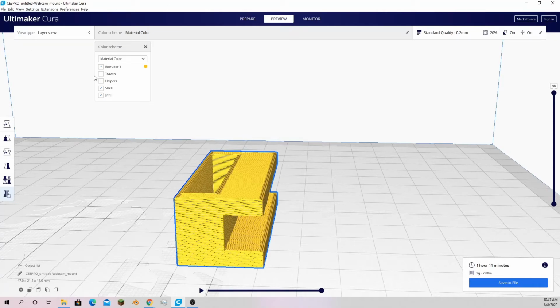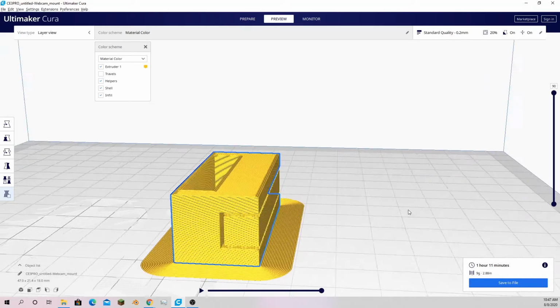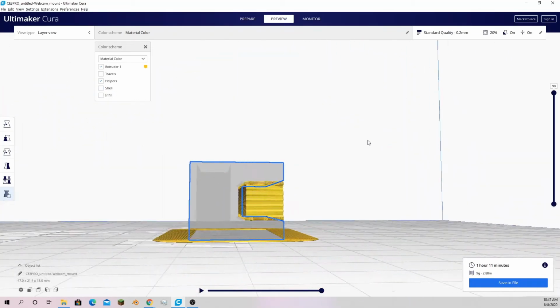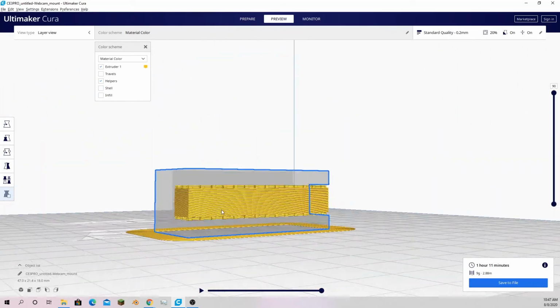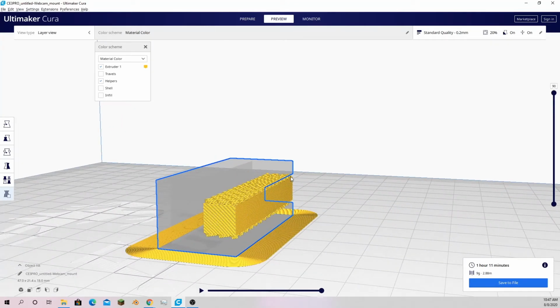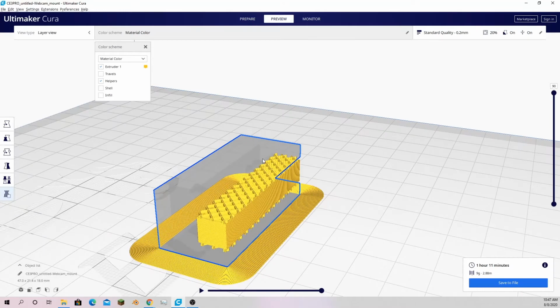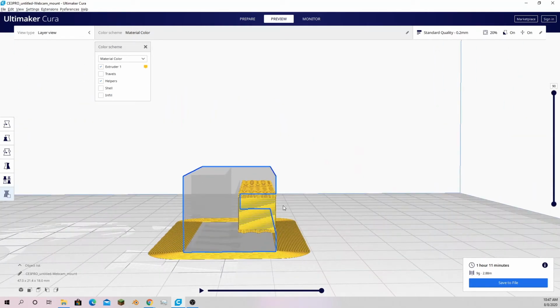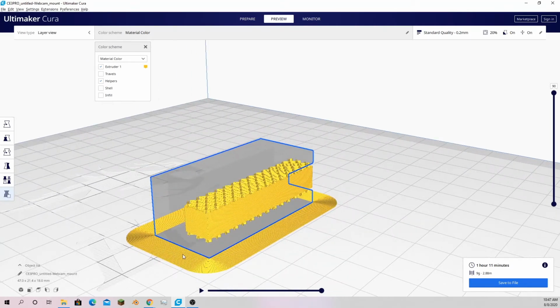You have to make it so that faces aren't intersecting, or edges or any sort of geometry isn't intersecting one another. Now we'll go into the infill right here, or not the infill, the supports. So here's the support, and the way it's printed, it prints out a small weak layer underneath and then prints out a thinner block of plastic and then another small layer on top. So this way you can easily snap it off your model and make sure that you don't have to worry about any support sticking to the model, or part of the model coming off, as it's really weak.